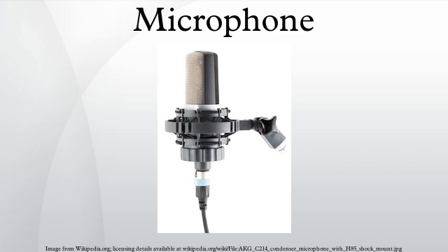Measurement microphones. Some microphones are intended for testing speakers, measuring noise levels and otherwise quantifying an acoustic experience. These are calibrated transducers and are usually supplied with a calibration certificate that states absolute sensitivity against frequency. The quality of measurement microphones is often referred to using the designations Class 1, Type 2 etc., which are references not to microphone specifications but to sound level meters.